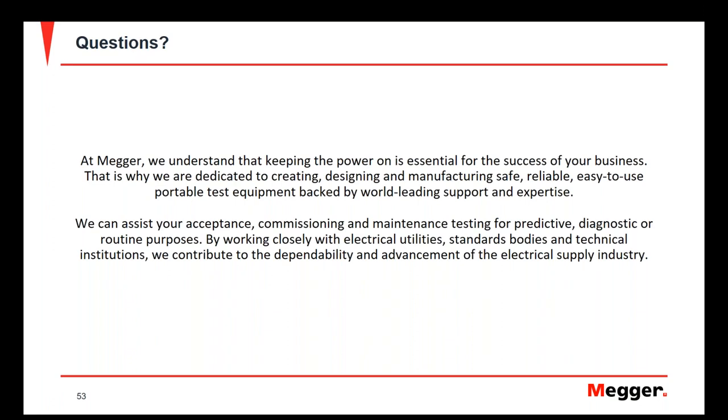Reclosers have high impedance, which actually varies during the test, more so in the case of oil circuit reclosers. So because of the reclosers having a high amount of impedance, to be able to test those reclosers, you need a test system with a high amount of output voltage.